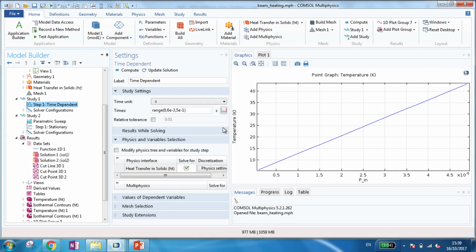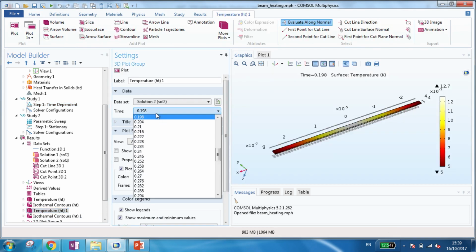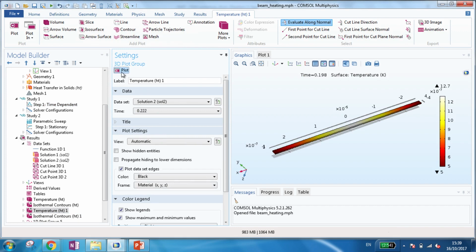But what you can do, again, you can put another cut and then plot the temperature of the central point as a function of time. And this is very important because what you see is that temperature starts from the base, and as the time evolves, you raise the temperature, and then eventually you asymptote to this steady state stationary that we actually solved together.